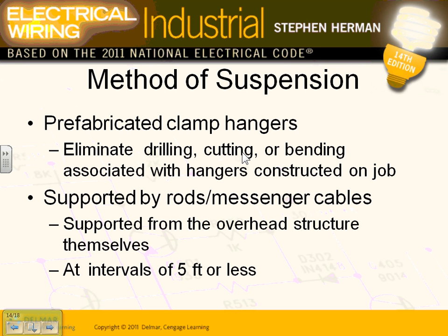Right now you can maintain it less because of these heat guns. You can point the heat gun at the bus, and it will tell you if it's hot. If it's hot, it means it has a loose connection, so you need to go torque it, tighten them. If it's not, you might be able to reduce the maintenance cycle. But all this equipment, guys, you have to do maintenance cycles with them.